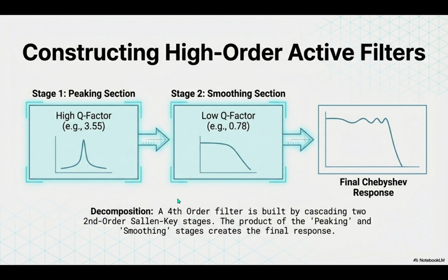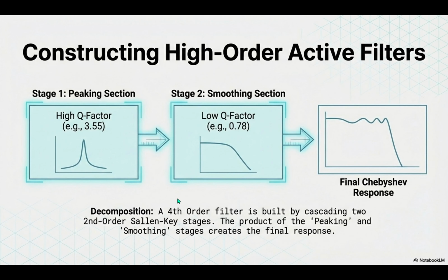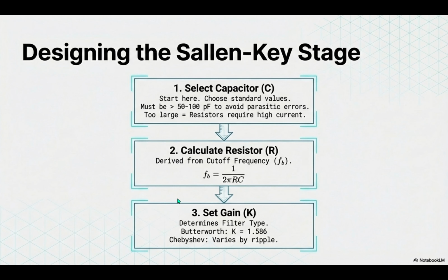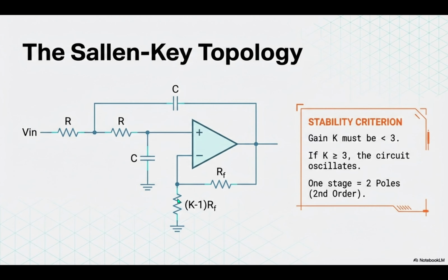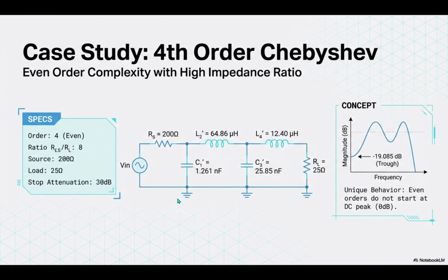The Chebyshev. It sounds aggressive. It's the sports car of filters. It handles corners incredibly well. It dives down into the stop band much, much faster than a Butterworth. But there's a trade-off. There's always a trade-off. Oh. What's the price we pay for that steep cliff? The price is ripple. Ripple. What does that look like?